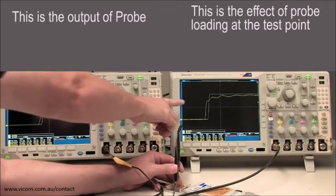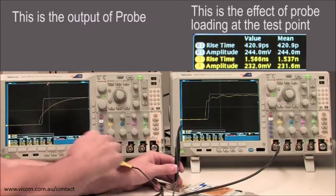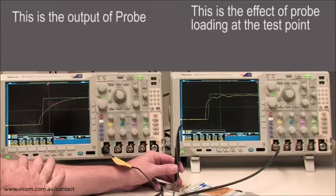Here's how a 1x probe with 100 pF input capacitance affects our source signal, which is a 244 millivolt step response with 420 picosecond rise time. The original signal has been degraded. The rise time is significantly slower and the amplitude has changed. Again, you have to ask yourself, what kind of harm is the probe doing at the test point?